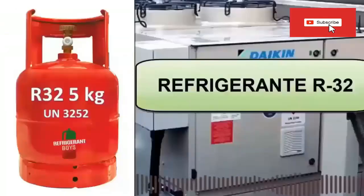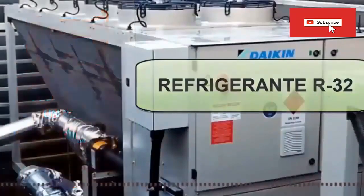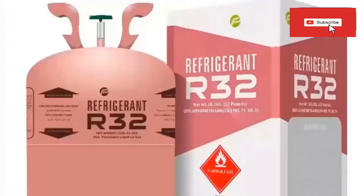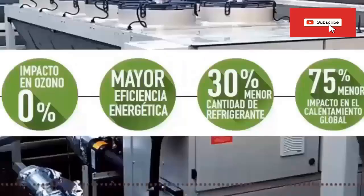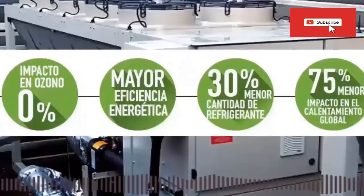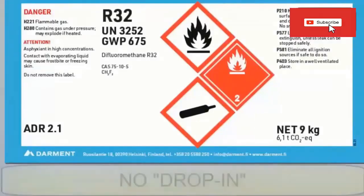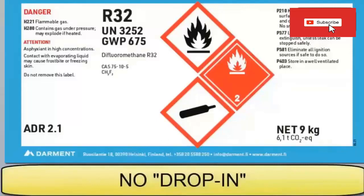1. R32 refrigerant is a refrigerant classified as A2L, slightly flammable, more energy efficient than R410 and with a global warming potential of 675. 2. Refrigerant manufacturers have clearly stated that R32 refrigerant is not suitable for retrofitting. That is, another gas should not be removed from a working piece of equipment and replaced with R32.